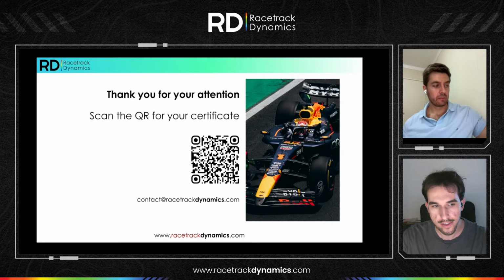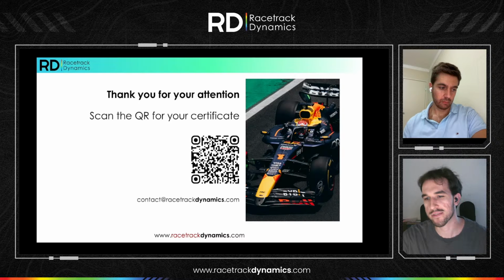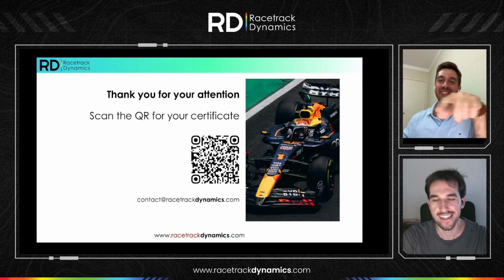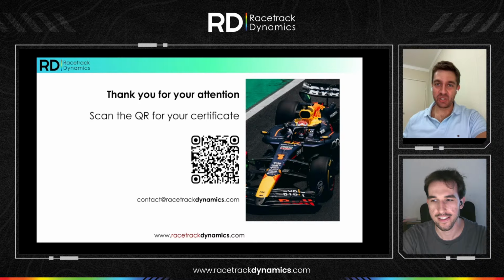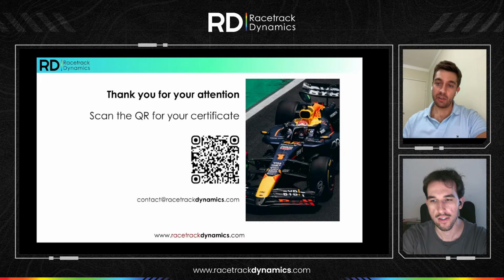Any more questions? Is Adams useful in this case? Somebody asked. I love this one. Yes, it is useful. If you haven't ever used it, good luck. As someone that has suffered or enjoyed, but more suffered, Adams for a number of years in the passenger car industry, it's good when you try to simulate complex stuff and you need to experiment with load cases, with compliances, and you need the very last bit of accuracy, and you have a very detailed simulation model.